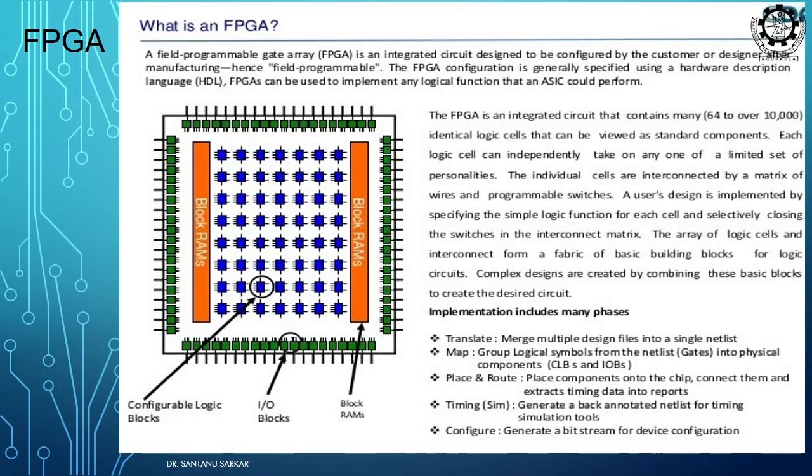So, one way to get a feel for how it behaves on silicon is to test it on your FPGA board. This FPGA board gives you so much programmability and flexibility that you can dump your design, check your output, and then if you are satisfied, you can go for ASIC verification or ASIC fabrication, or you can redesign and proceed again. So, this gives you a platform for trial and error. Okay. This is comparatively cheaper, because you can do testing several times, right.